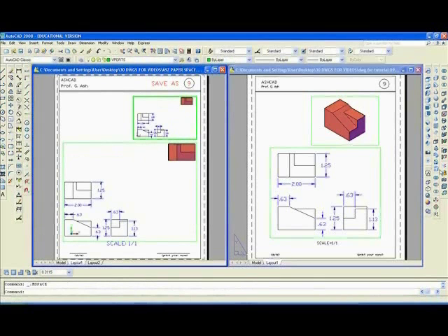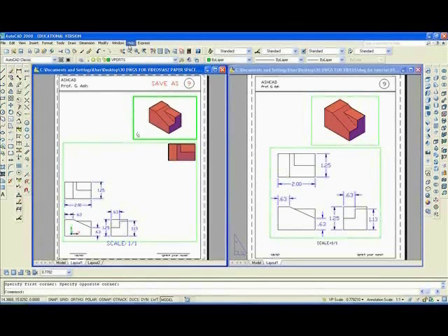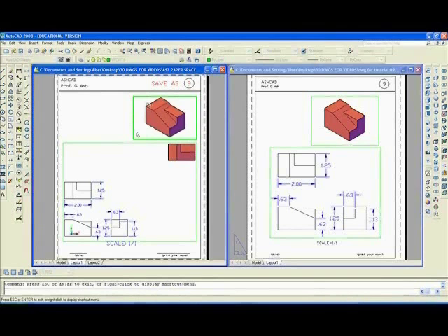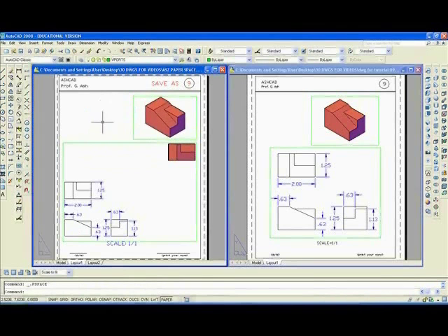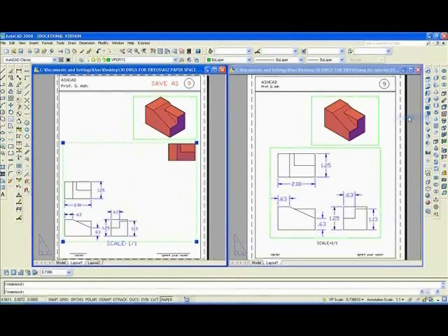Double click inside. Then go to Southeast Isometric, pan, and zoom. Zoom real time to make it even bigger. Double click outside to get back into paper space. Click on the large viewport and go down to annotation scale and select 1:1.